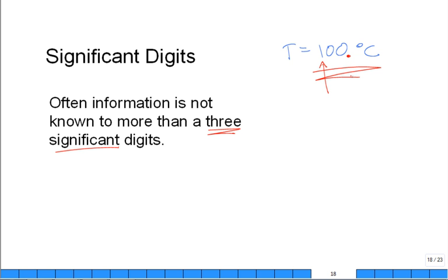Okay? Just assume that if somebody said the temperature is 540, that's 3 significant digits on the temperature. Or if they assume it's 1 megapascal, it's 3 significant digits on that, kind of as a baseline for your inputs, unless something really tells you that no, it's 100 degrees C plus or minus 20 degrees C or something. Really uncertain in your temperature coming in. But if most of the inputs are known to 3 significant digits or more, what's the maximum your output can be known to? 3. You can process all those through the calculation.